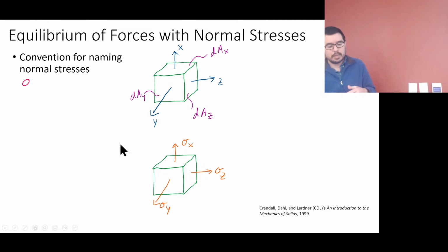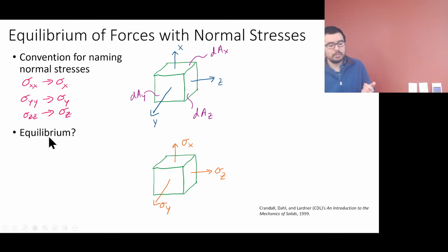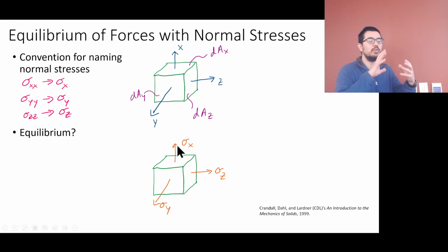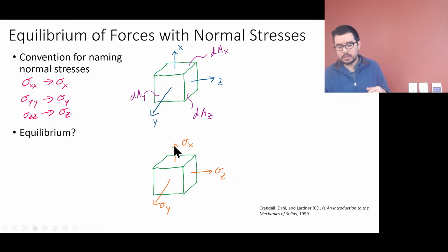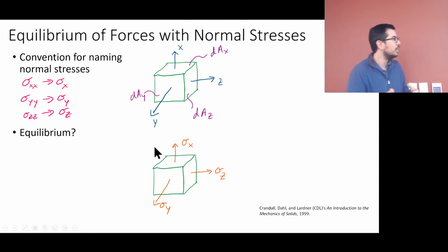We already discussed this is the convention. All right, let's look at equilibrium. Look at this. If you just took a cube and you put a force, in this case a stress times dAx, sigma x dAx is going to give you the force on that face.